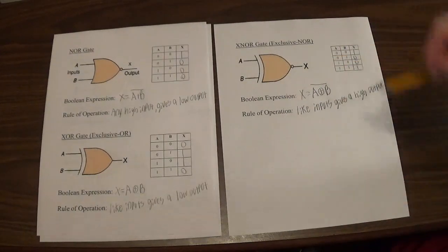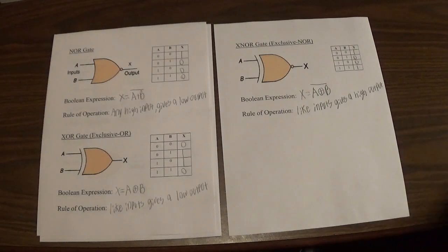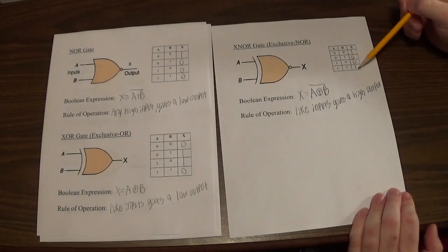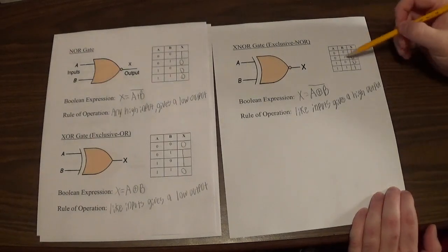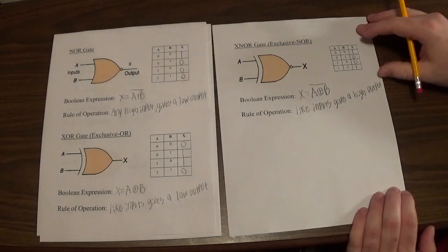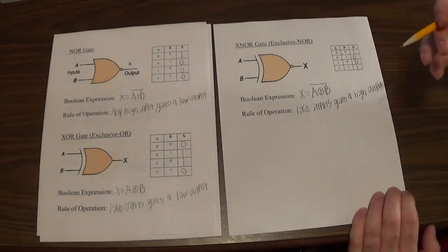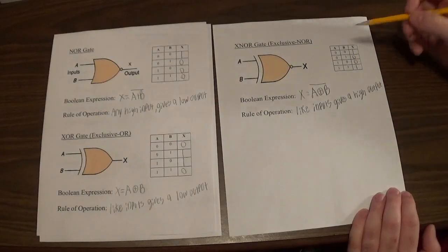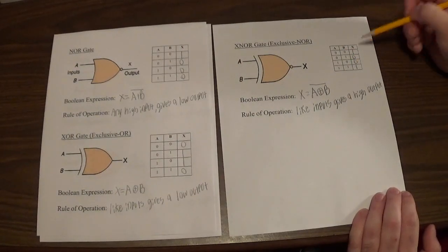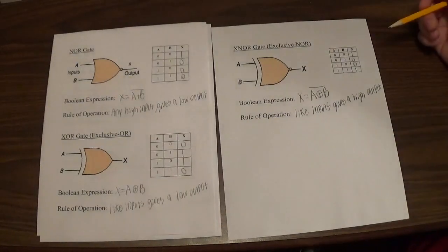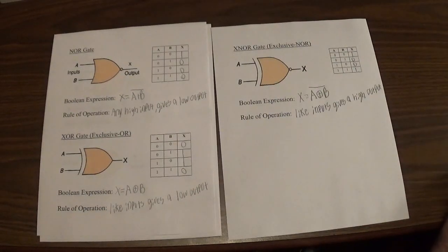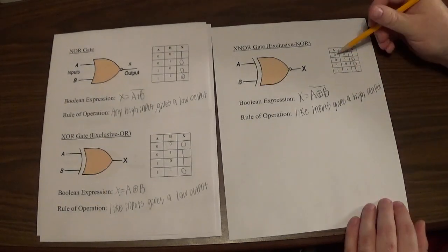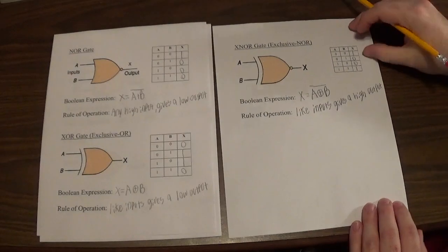Okay, so it can be used in the same type of application that we just talked about for a different purpose. So here, if they're both off or both on, then the output is on. If for some reason they're different, then it gets a 0. So that could be used to turn off the process, to shut it down basically if the switches don't agree. But as long as they agree and they're the same, you get a high and the system is allowed to run. So just a different application there. Okay, so here, like inputs, if they're both 0 or both 1, we get a high output.